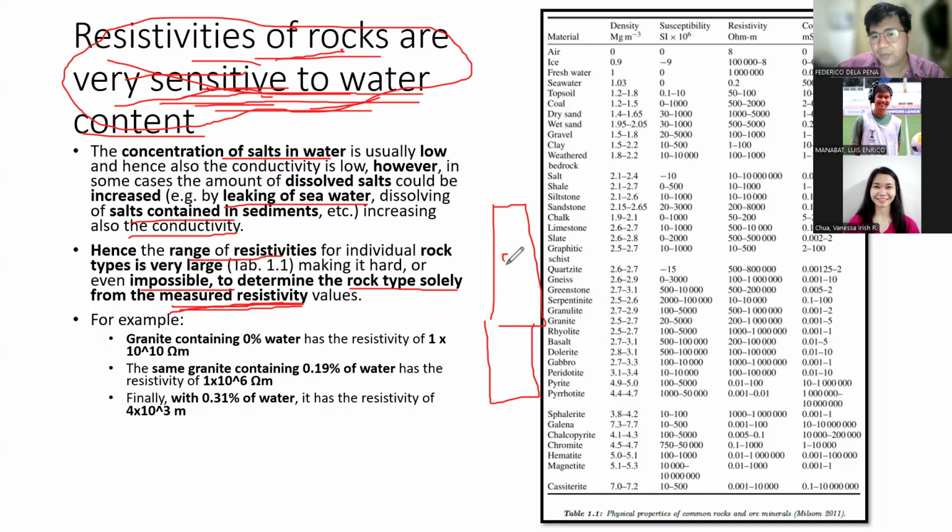Just describe what soil type you have, what the rock type is, and what their probable depths are. You can construct a rough local stratigraphic column from doing some field work, studying the geomorphology of the site, looking for outcrops.